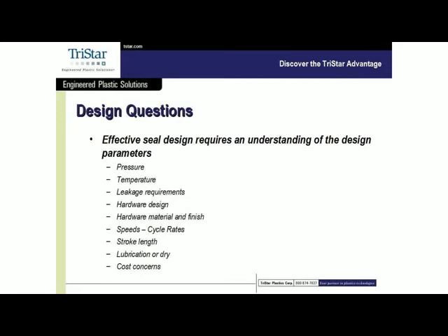How many feet per minute? What's the cycle rate? How many strokes per minute are you running? What's the length of the stroke? Is it lubricated or is it dry? We have a lot of dry pneumatic applications where spring energized PTFE is very, very good in those environments. But is the lubrication, is it Skydrol, is it mill oil, just exactly what it is.